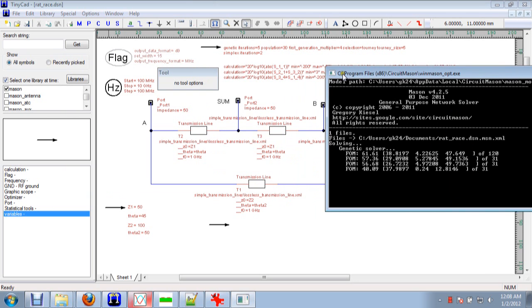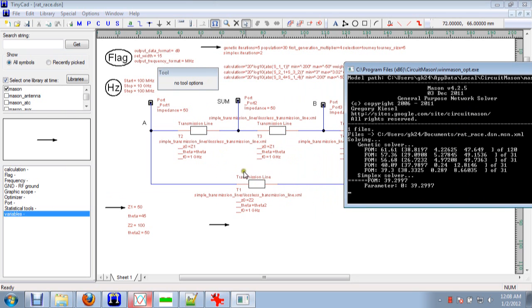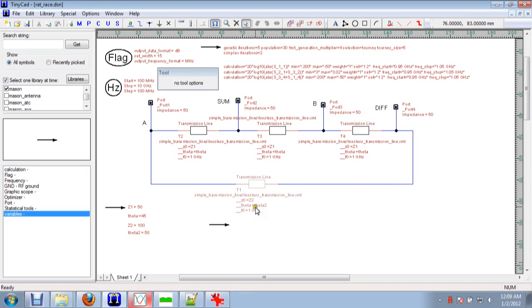Now, the problem is we have a number of values that will sort of work for the impedance and the electrical length. So if I update this, we end up with the 90 ohms impedance that it thinks it should be, and the electrical lengths are wrong. The problem is, in reality, what we really want is this to be 3 times longer than that.